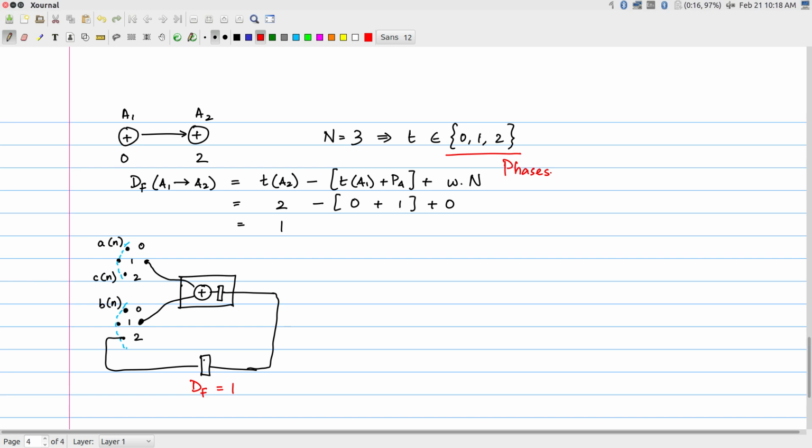So depending on the phase of the clock, I will essentially get different values being applied to the inputs of the adder. Okay, and each of them correspondingly are implementing one of the operations in the data flow graph. Okay, so that is where this DF essentially becomes useful.